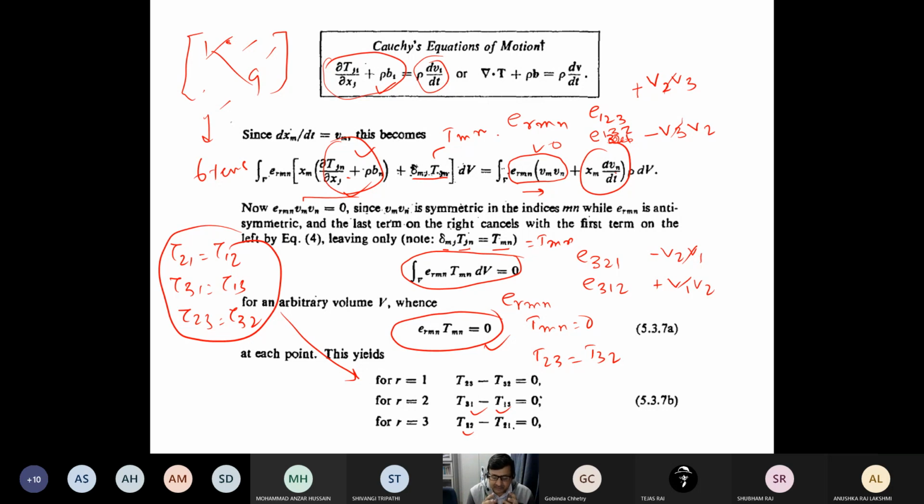What are the invariants? What are the eigenvalues? And from there, how does the pressure originate? How do we separate out pressure in order to identify the deviatoric part of the stress, which is generally correlated as stress being proportional to strain? When you say stress, it is nothing but the deviatoric stress, which doesn't have the pressure component.